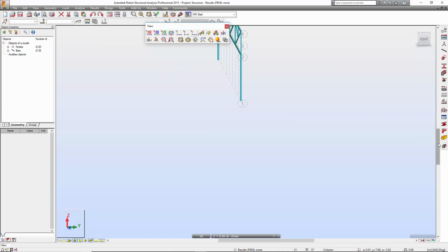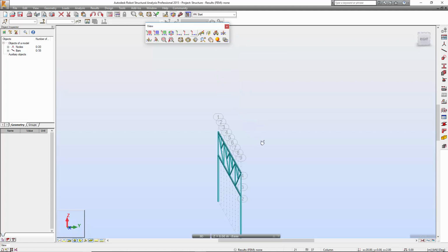If one direction is unstable, what we need to do is modify the model a little bit, the structure in here. For example, normally the structure at this joint, when the column connects to the truss, they will have a hinge connection, supported by a hinge from the column head and then connecting to the truss. If you want to do this hinge connection, which we have maybe practiced in the other examples already, we use the release to do this.